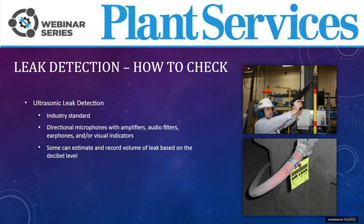Ultrasonic leak detection, like I said, requires specialized equipment. You can see an image there on the right, and you can see the tag underneath it. But they do have distinct advantages. It can be done from a distance. You can discern the leaks in a noisy environment. And it's also going to give you an estimate of the volume for that leak. And this can help you prioritize which leaks to fix first.